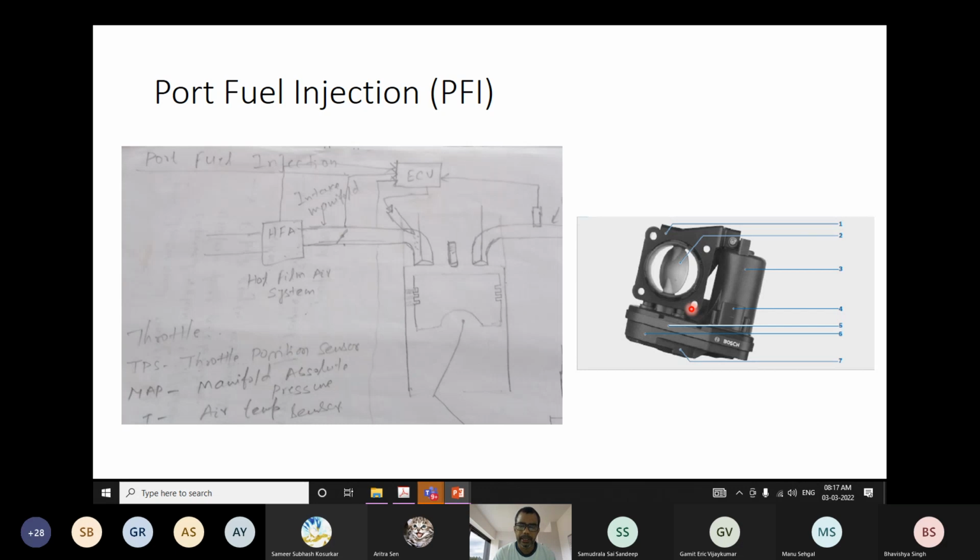Now it is a torque based demand system, where the throttle opening does not depend only on the accelerator position, but the ECU also sees whether the whole vehicle requires some extra power to run some of the other parts. Then the ECU decides the throttle opening based on the acceleration signals and the requirements of the other power. That is called torque based demand. If the calibration is based on torque based demand, then the acceleration signals will not go directly to your actuator, the throttle opening. The calibration changes depending upon how well we want to control the engine.